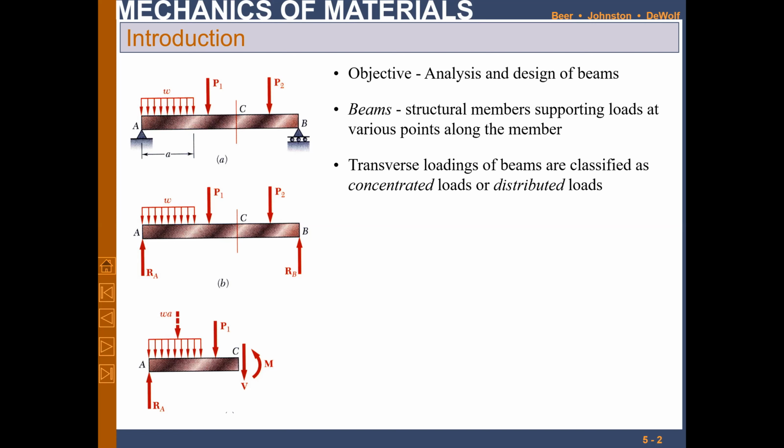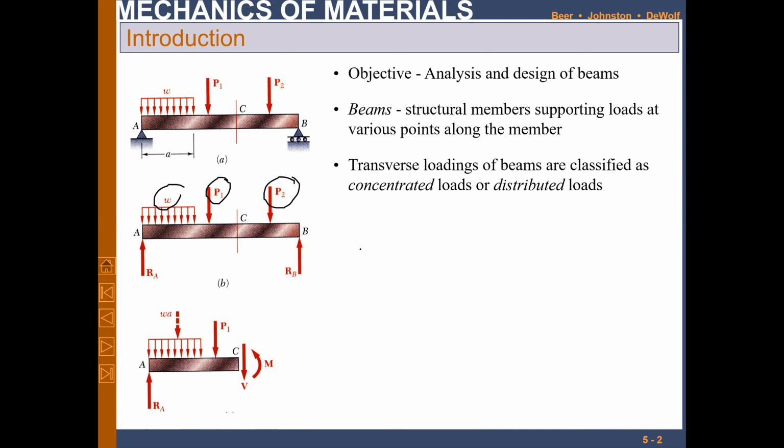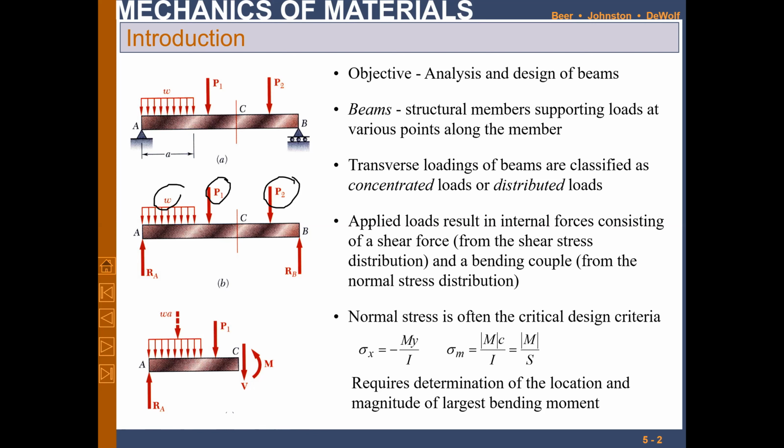And transverse loading, we already know, is the loading that is applied perpendicular to the longitudinal axis of the beam, and it is further classified into concentrated loads as well as distributed loads, like this one. Sorry, these are the concentrated loads, and this is basically the distributed load, right? And then the applied load results in internal forces. These are all the internal forces which are causing the stresses.